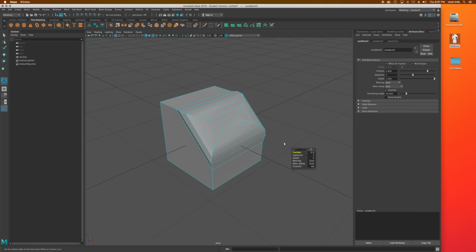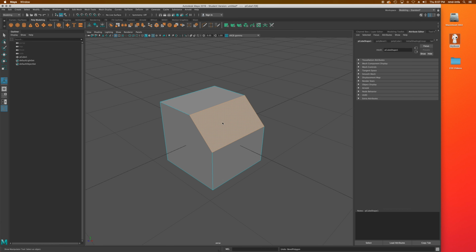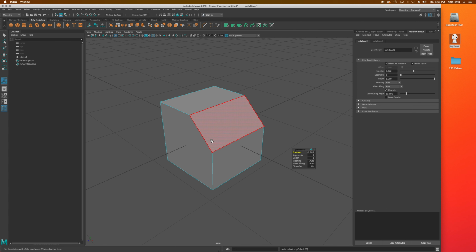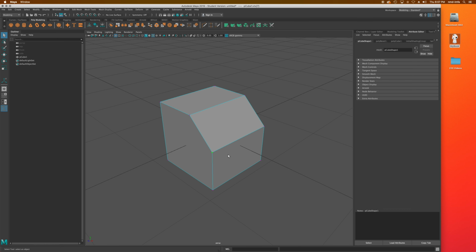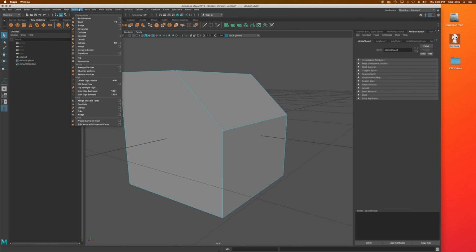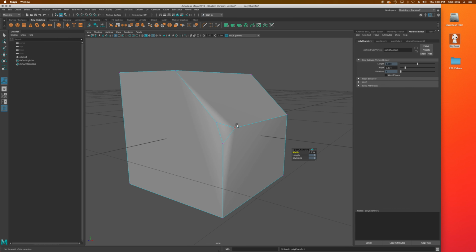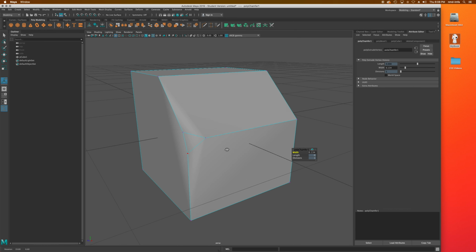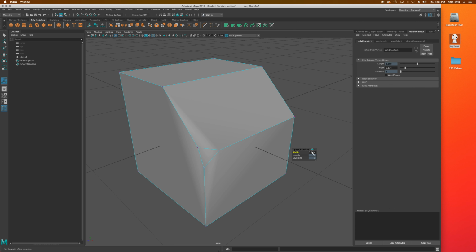I can also do this to a vertex. I mentioned that. So if I go to a vertex, it's really just going to subdivide it, and this is very similar to chamfering on a vertex. So I can take a single vertex point and I can go to Edit Mesh and again bevel, and you can see it just subdivides it into 3. It does smooth it out, which is fine, but I could go to like 0.5 and it's going to go a lot bigger. So that's an interesting tool for making another face there, subdividing it a bit, right?